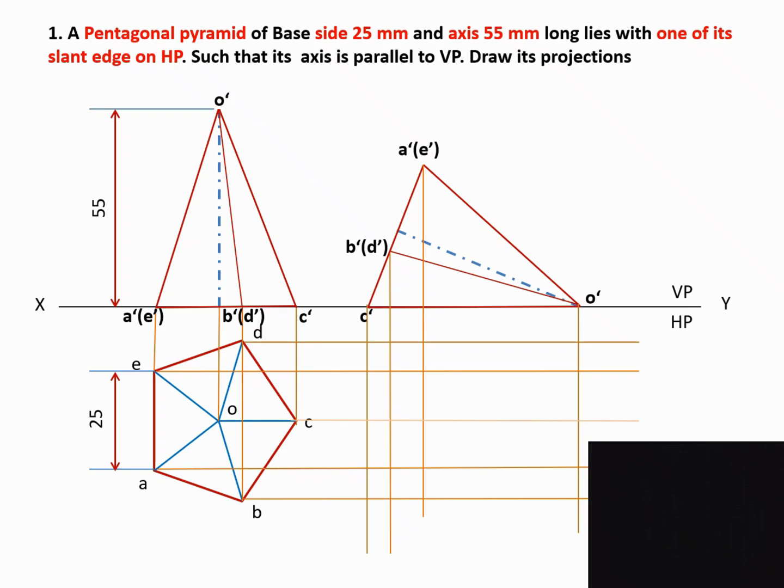So like this we have to mark every point. So how it is, I will show you. First E. So this is the E line. So here this is the E line. So you have to mark E here. So this is how we are going to mark all the points. So first I am going to mark the first point A1. So first this is A, and the A line from the projection point is here. So both A lines coincide at this point. So you'll mark it as A.